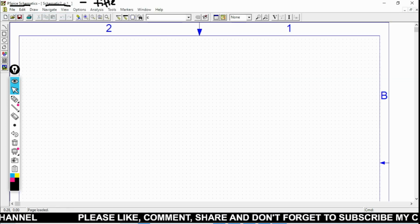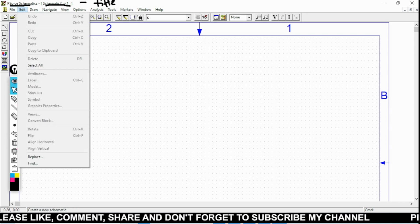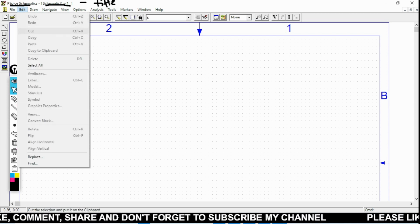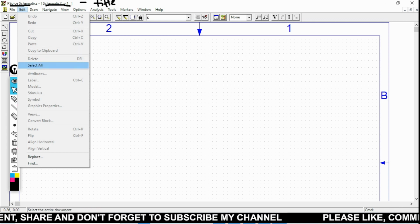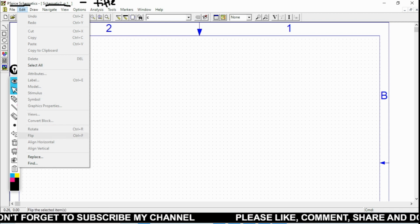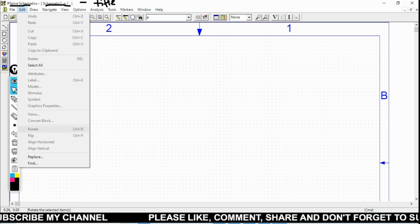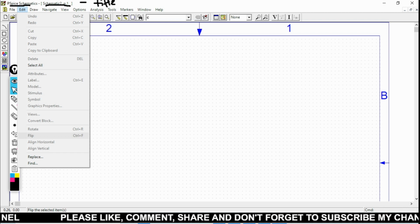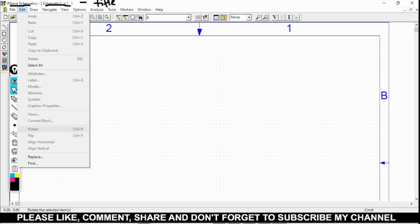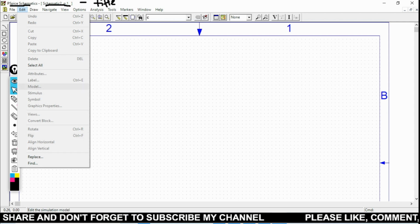So I am going to take a new project, then I am going to save it according to my need. Edit is the same as in the others: undo, redo, cut, copy, paste, delete, select all, and all these things are here. We are going to use rotate and flip, these two particular things, when we are using this software. So keep in mind, the shortcut for rotate is Control R, and for flip it is Control F. When we are using an electronic component, if we want to rotate that component, we use Control R, and if we have to flip it, we use Control F.